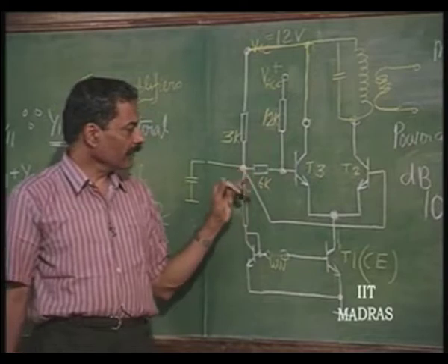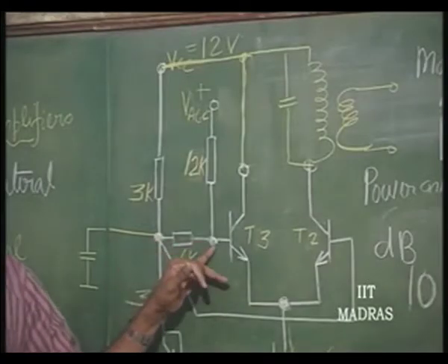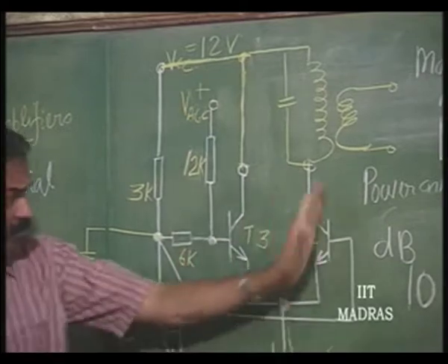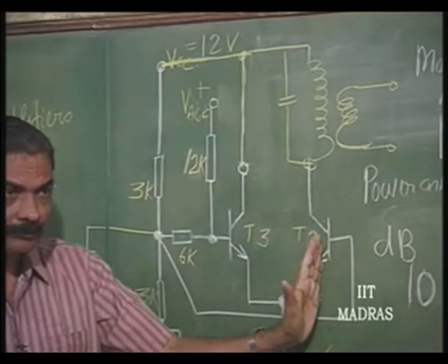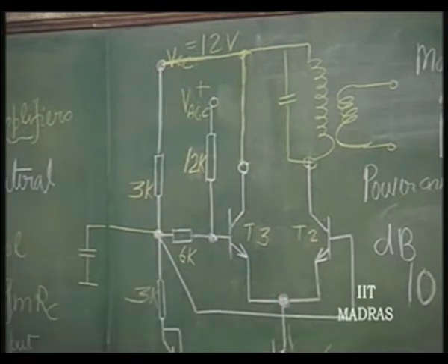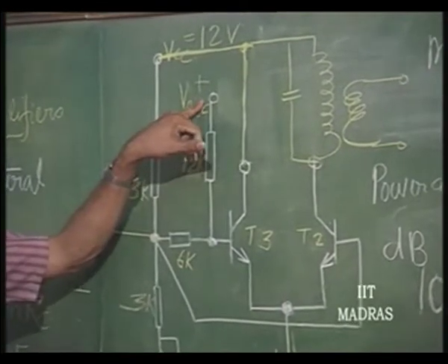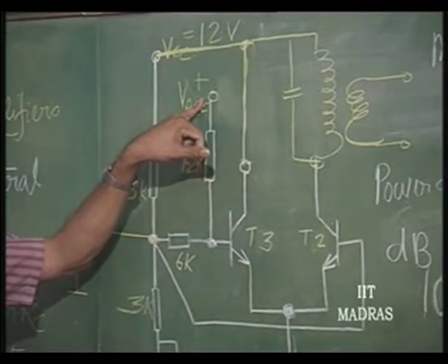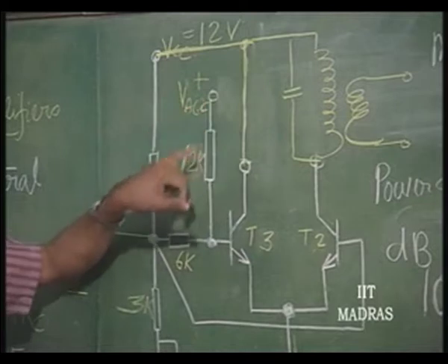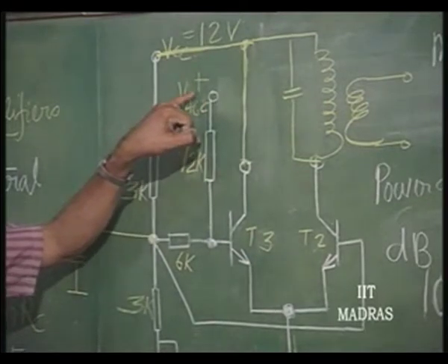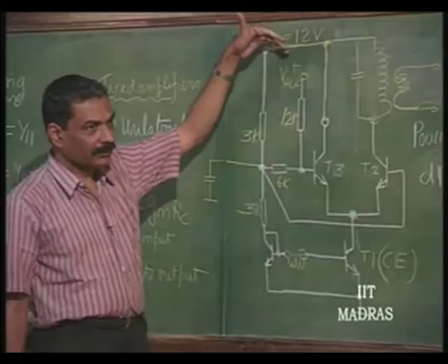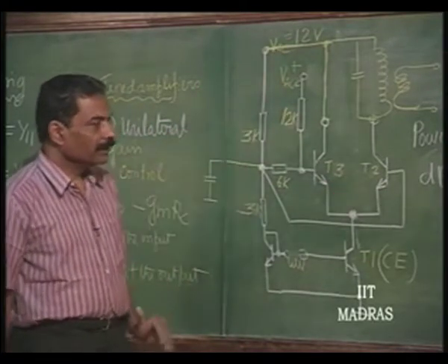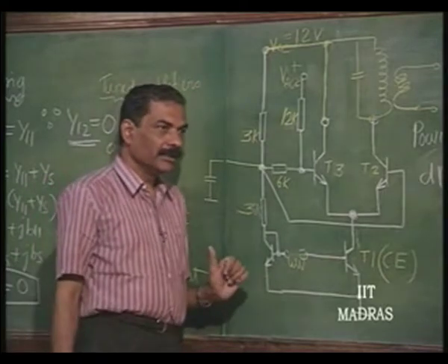This is 0, therefore, this is at a positive potential and this is at a lower potential, and therefore, all the current is diverted to this. So, the gain is maximum when VAGC is 0, and when VAGC is 6 volts, the gain is half, GMRC by 2 or whatever it is, and then when VAGC goes positive, okay, by some value, then the gain can become very low.